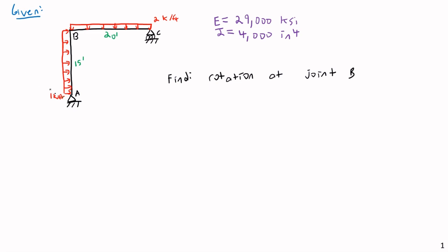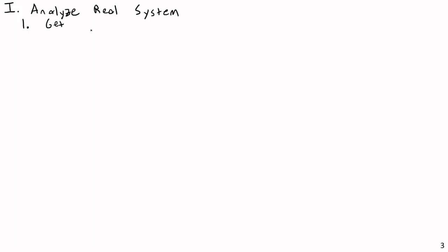I could draw an exploded view right off the bat and solve for the internal reactions or the internal joint forces. But in this case, it makes more sense to start with the external reactions. Just looking at this frame, this speaks to me as saying, let's get the external reactions first. I can't spell the word first today.